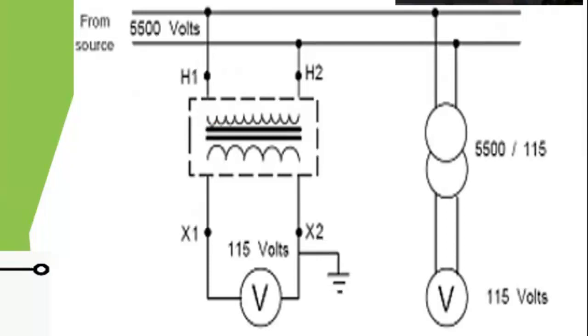That is the high voltage terminal of the transformer. Then the low voltage terminal of the transformer will transform that high voltage to what? A 115 volts that could be read or used for control. But in this case, it is for monitoring purpose, for us to know what is happening in the main circuit. So what we have here is a step-down transformer looking at the main circuit.